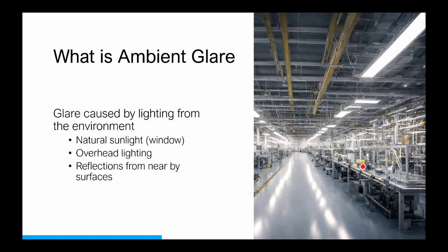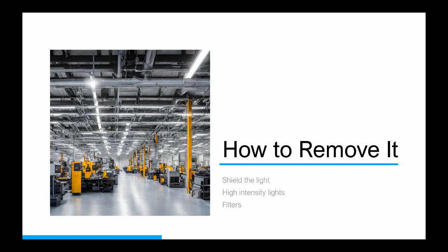What was happening is the light from the machine vision light was reflecting off the shiny materials on their machine and going into the vision system and causing problems. So that's not something we would have been able to predict in our testing lab. We don't have shiny parts around our testing stations, but something that they came across once the system was implemented in their space. So when that happens, how do we remove it?